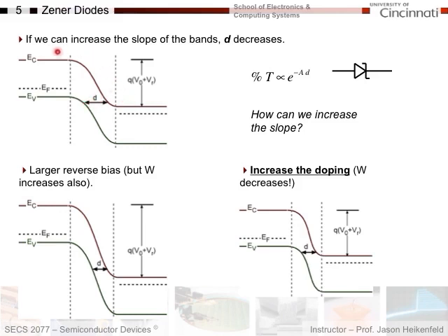We've always assumed they go like this. They go over the top of the conduction bands and along the valence band as well. But through this barrier, what if they could go straight from here to here or from here to here? If I do that, I could get a different type of current, which would be proportional to the percentage of tunneling. It would be a tunneling current through that barrier.